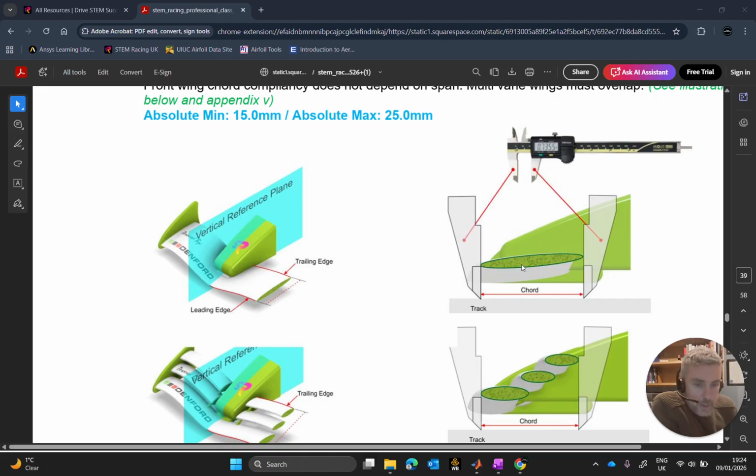parallel to the track. Now, with such a slight angle of attack there's not going to be very much between what the chord line measured chord is and what this technical document's measured chord is. What it looks to be is effectively the cosine of the angle of attack times the distance from the foremost point to the aftmost point. Yeah, so maybe it's just something to clarify there.